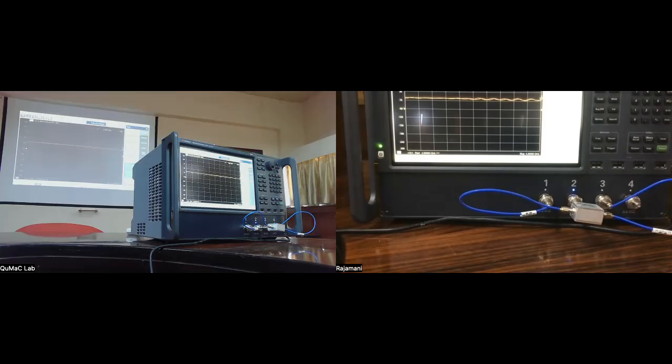So there are standard tricks, like small size and choosing the right resistance material. Usually for high frequency circuits, they will use a nichrome alloy, which can give you a lot of resistance in a very small package. You can buy surface mount resistors, right? They also come in different sizes. It can be this big or it can be very, very tiny. The general rule of thumb is that if it's smaller, it will work to higher frequencies. But then it has to be also packaged correctly, because you cannot have a voltage divider network on a breadboard or a printed circuit board with wires sticking to it, right?